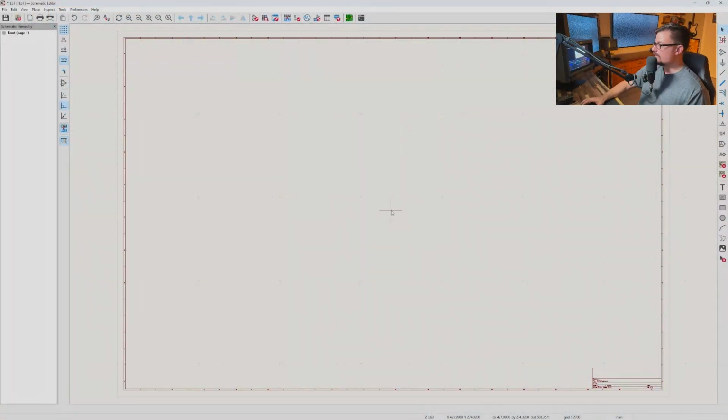So when you make a signal flow drawing, the mistake I made at first, you don't want everything to interweave together and look sloppy. You want to be able to read it from left to right, just like a standard document. Just do it. The reason for this, we want our inputs on the left side, our connection devices in the center, and our outputs on the right. So since we know this, you can kind of go, well, I want to hook up two TVs. I've got two TVs in my room. So we're going to make a square.